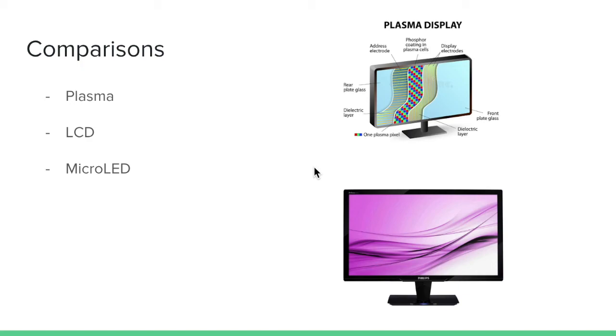Micro LED screens are a very new technology, with commercial screens appearing on the market for the first time this year. These new screens are the only ones that can emit a higher brightness than OLED screens can, and are also more energy efficient. Despite the higher brightness, micro LED has a longer lifespan than both OLED and LCD screens do. OLED has less flexibility in the sizes available, whereas micro LED can be fitted to any size that is needed.